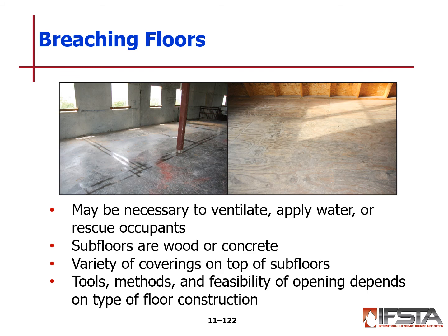To breach the floor, this may be necessary to ventilate, to apply water, or to rescue occupants. Subfloors are wood or concrete. There is a variety of coverings on top of subfloors: you can have carpet, you can have tile, you can have hardwood decking. Tools, methods, and feasibility of opening depend on the type of floor construction.